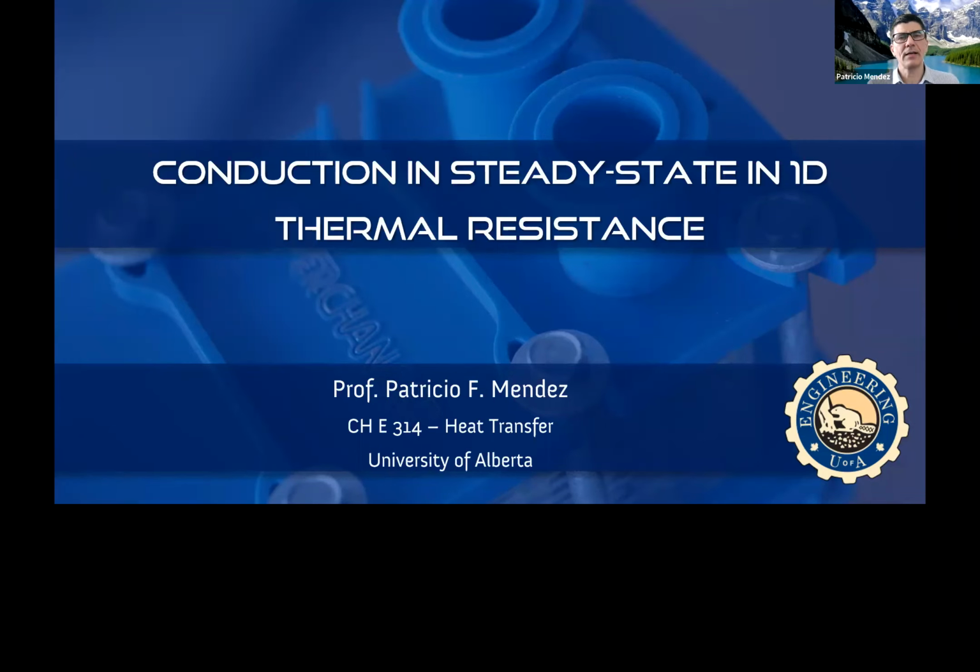The heat in and heat out, we discussed it, but we didn't say how it came in or out. So in our week 2, we said, okay, these are the mechanisms through which heat can come in or out to the control volume. In week 1, we had discussed advection, but in week 2, we discussed convection, radiation, and contact, and conduction.